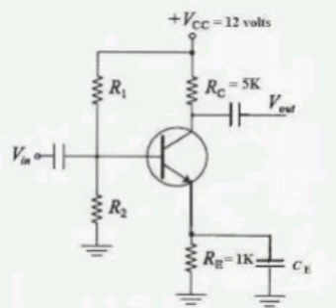Now flat band voltage VFB equal to phi ms equal to phi m minus phi s, that equals 5.2 minus 4.181, that equals 1.019 volts. Phi f, the Fermi potential, equal to Vt natural log Na by Ni, that equals 0.026 natural log 10 power 17 by 10 power 10, that equals 0.419 volts.